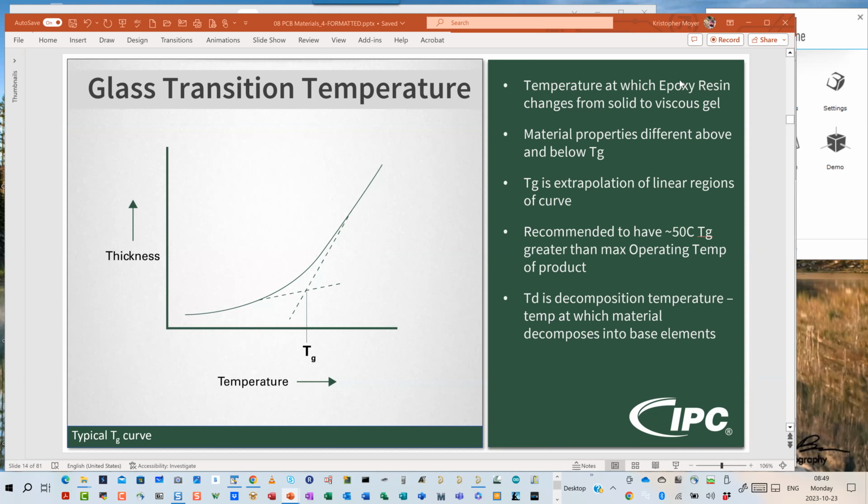Normally, you're looking at mechanical issues. The issue you're going to be running into, though, with digital and standard analog systems in those higher temperatures is the parts themselves becoming unstable. Op amps, your digital chips, right? Your FPGAs and so on start operating in an unstable condition, right? An unknown unstable condition. What that's going to do to your system, I don't know. That's why you're doing the stress screenings and stress testings.